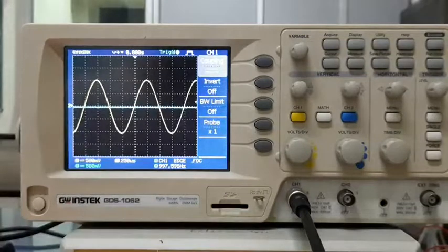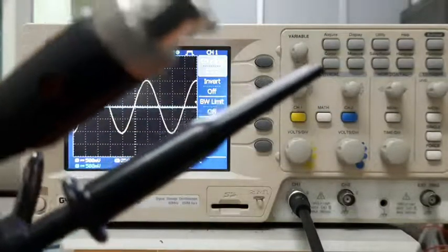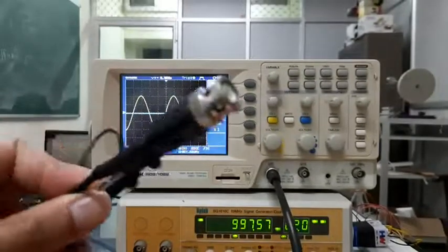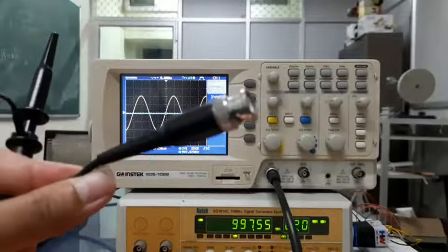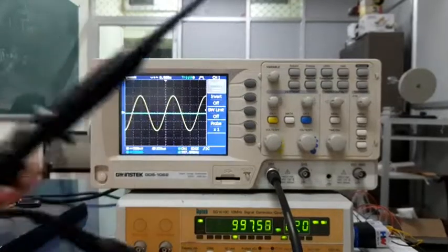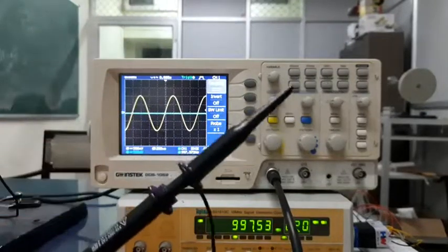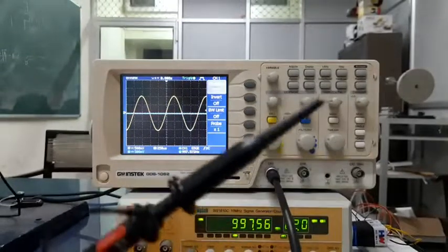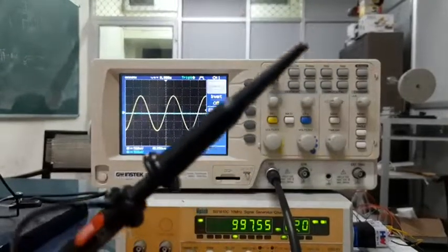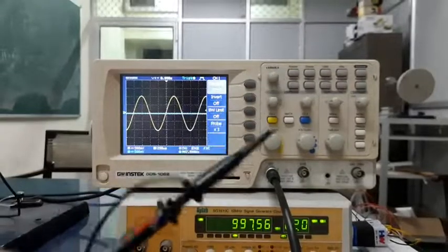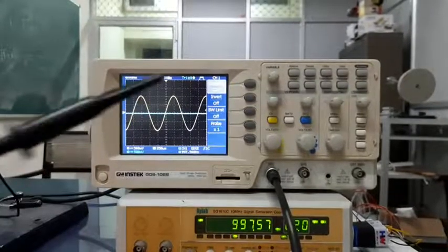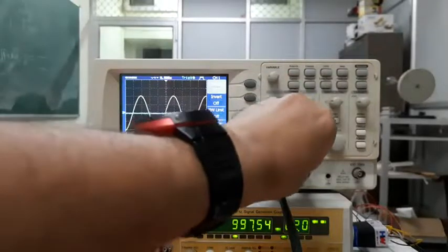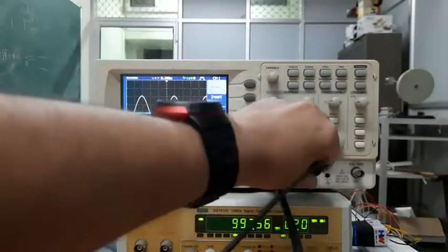And one of those looks something like this, right? So it's a cable which looks like this. One end looks like a BNC connector. Another end looks like this. This is called a probe, right? And it's especially made for oscilloscopes. So you have been provided two of these cables because you have two channels, so that you can attach two probes to this. The BNC end goes to the oscilloscope, right?